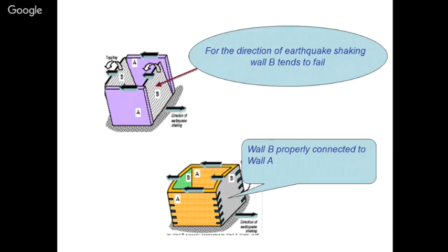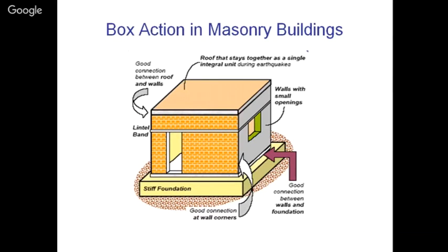Here they have shown two figures, in which one is not connected properly, where you can have a roof collapse, and the one which is properly connected maintains displacement of the diaphragm level as well as of the walls along with each other. That action, that phenomenon, we can have when we are using bands. Bands provide connectivity to your walls: wall to wall, wall to cross wall, wall to slab, and piers to the spandrel.